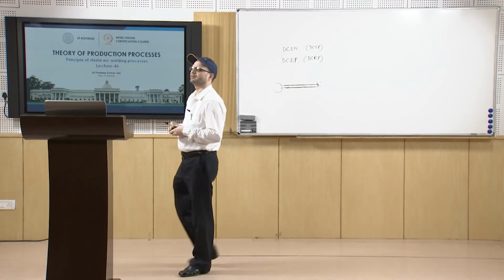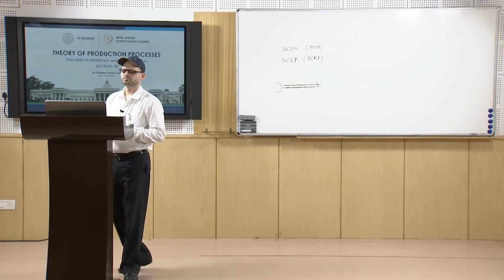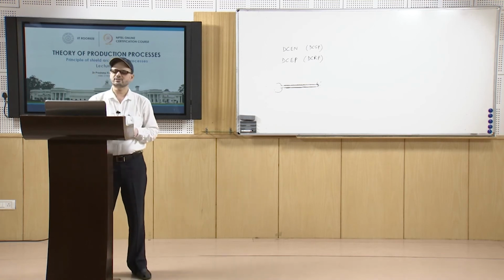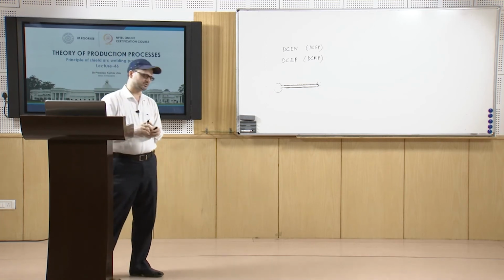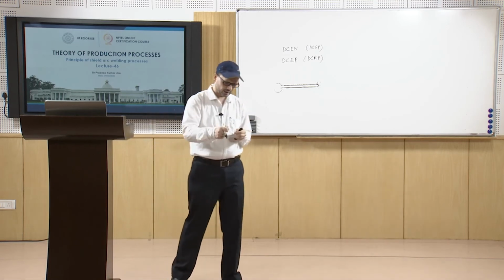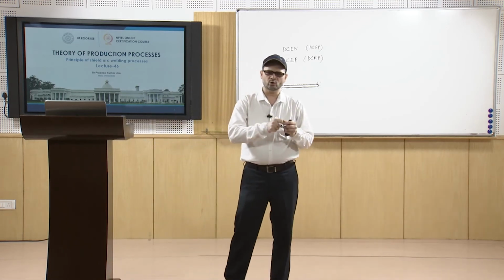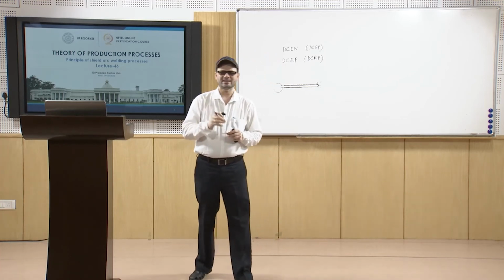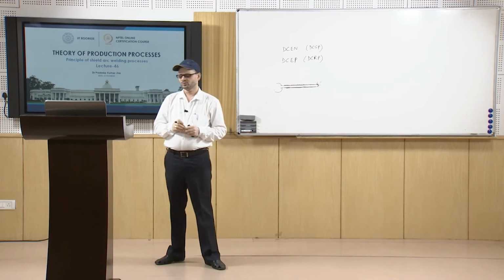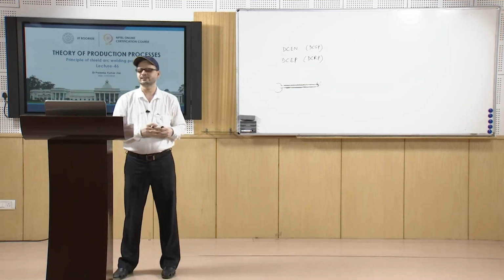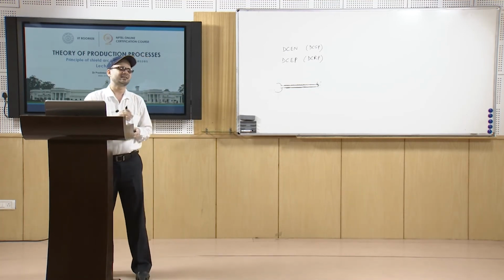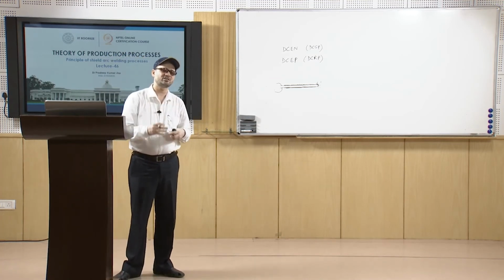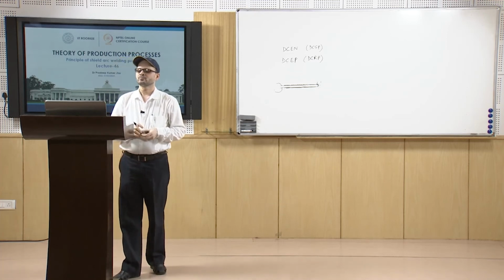However, there are certain limitations also. What are the limitations? When we use the electrode, since the current passes through the electrode, whose central core is metal, because of the resistance it sometimes gets heated, and then the covering may break down, which may alter the arc characteristics many times.